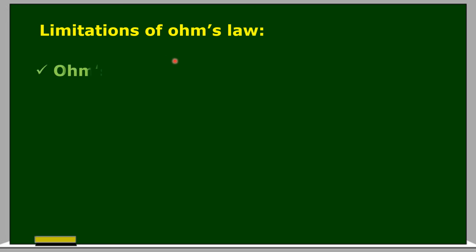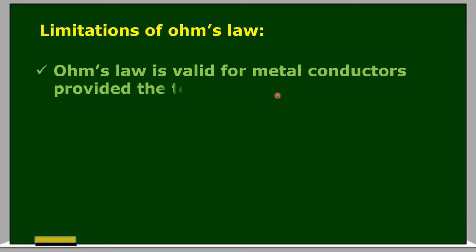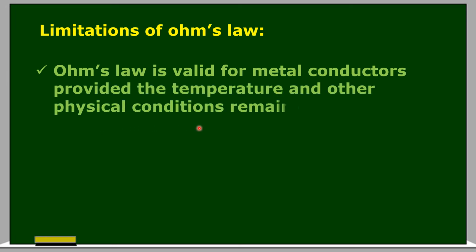Now I am explaining the limitations of Ohm's law. Ohm's law is valid for metal conductors provided the temperature and other physical conditions remain constant. The resistance of a conductor is temperature dependent. If temperature changes, the resistance also changes.